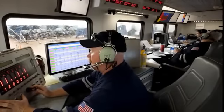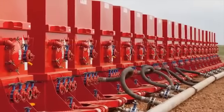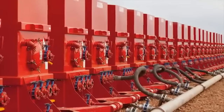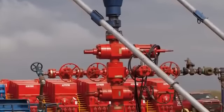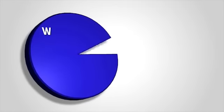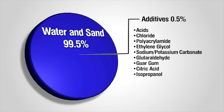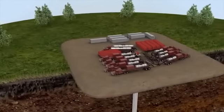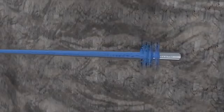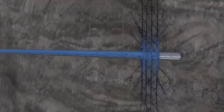The process consists of pumping a mixture of mostly water and sand, plus a few chemicals, under controlled conditions into deep underground reservoir formations. The chemicals are generally for lubrication, to keep bacteria from forming, and help carry the sand. These chemicals typically range in concentrations from 0.1 to 0.5% by volume and help to improve the performance of the stimulation. This stimulation fluid is sent to trucks that pump the fluid into the wellbore and out through the perforations that were noted earlier. This process creates fractures in the oil and gas reservoir rock. The sand in the frac fluid remains in these fractures in the rock and keeps them open when the pump pressure is relieved. This allows the previously trapped oil or natural gas to flow to the wellbore more easily.